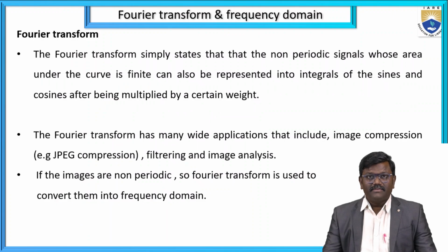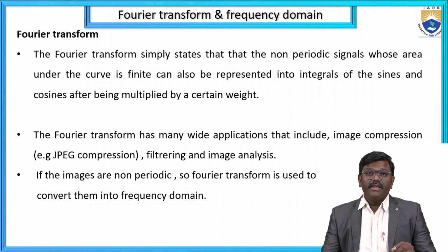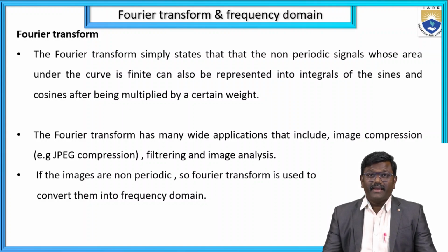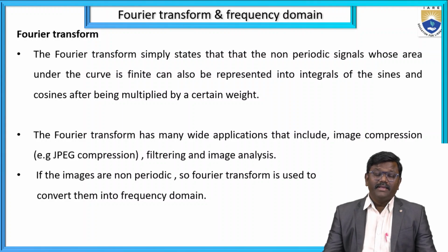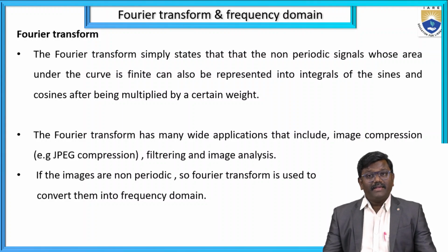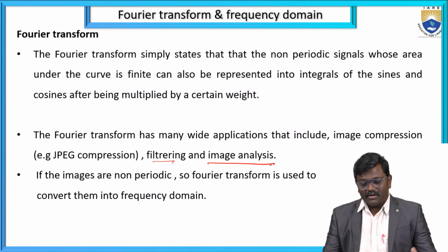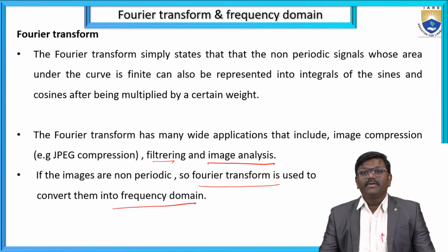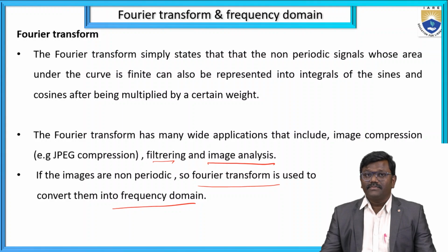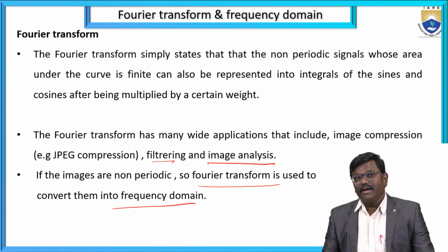So, once you understand the Fourier series, let me compare it with the Fourier transform. The Fourier transform simply states that a non-periodic signal whose area under the curve is finite can also be represented as integrals of sines and cosines after being multiplied by a certain weight. The Fourier transform has many wide applications, including image compression, image filtering, image analysis. If the images are non-periodic, the Fourier transform is used to convert them into the frequency domain. That is the major importance of the Fourier transform compared with the Fourier series.